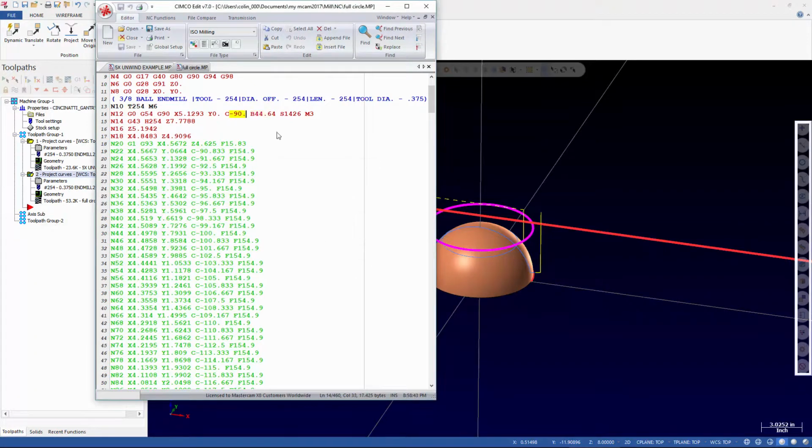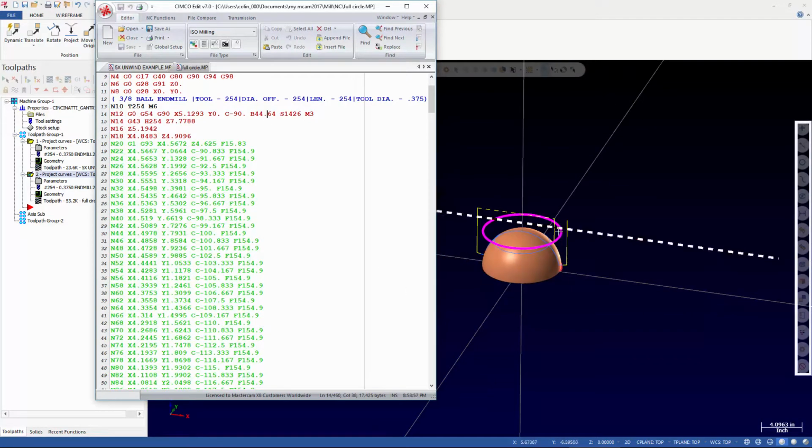This is where we have to rotate C90 positive or negative in order to get our B axis into position. And so that's what we want to try and avoid when we're setting up the machine. But in order to do that, we also have to make sure that our geometry is set up correctly.